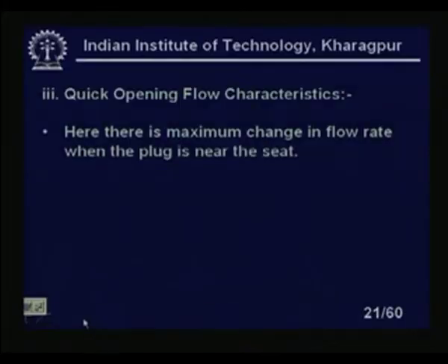And in the case of quick opening, initially, when the plug is very near to the seat, you will find there is a large flow, and whenever the plug is going far from the seat, as we move the stem upward, there will be a little change of the flow even though there is a change in the stem position. Okay, that is basically quick opening characteristics.